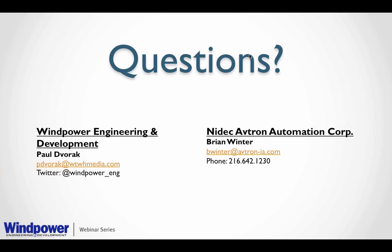Hey, Carlos asked a question. What's the resolution that magnetic encoders are offering? That's a good question. It varies on the vendor. For example, Avtron out of the gate offers somewhere between 3,072 counts per revolution all the way up to about 5,000 counts per revolution on most of our models.